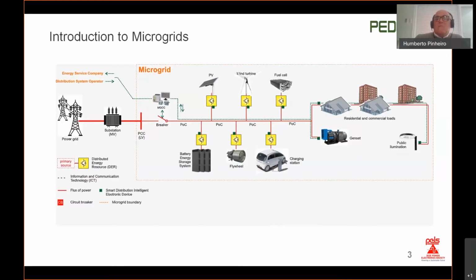control system communicates with the DERs and the controllable loads via a low bandwidth communication channel, in the island mode, for instance, at least one distributed energy resource must be responsible to keep the voltage and frequency within the nominal values. So when more than one DER is responsible for controlling the voltage and frequency of the microgrid, it's required that these DERs have some power sharing mechanism.